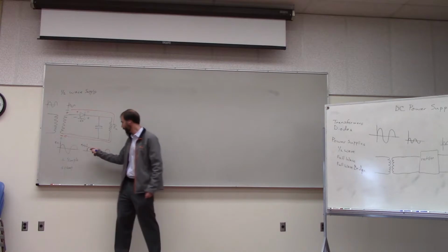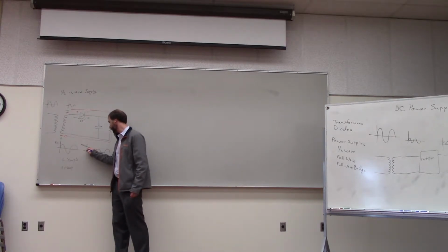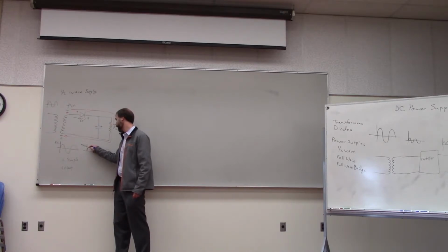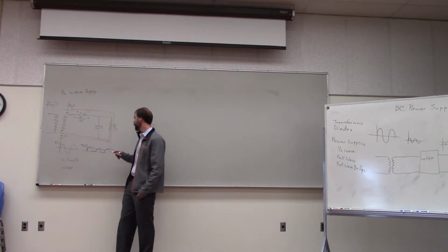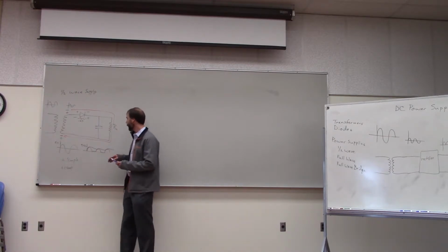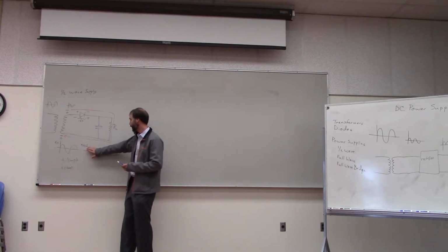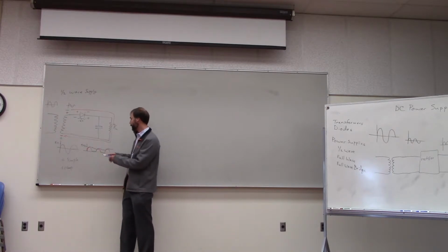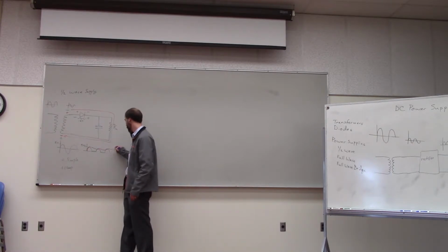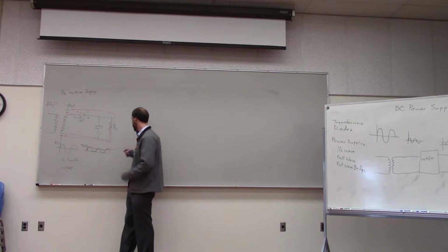So basically, when the power is going up, the capacitor is charging up, and then in between, the capacitor is discharging, exactly. And then it charges up again, and then it discharges. So if you put this capacitor in there, you wouldn't see the red and green parts. You would just see this blue line. It would look sort of like this.